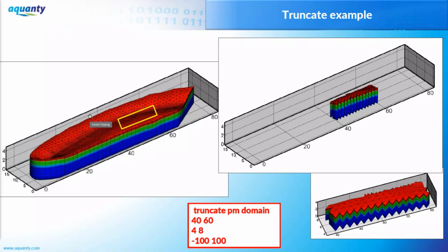The first thing that happens when hsplot is run is it actually produces this plot control file if it's not already found in the model folder. The other thing that I should point out is that the contents of the plot control file are also dictated by the contents of the model outputs. So for example, if you run a flow only model, you run Grok, you run PHGS, you run Hsplot, then the plot control file will contain a bunch of information regarding flow variables, but it wouldn't include information about concentrations because at that point, the model is not a solute transport model.